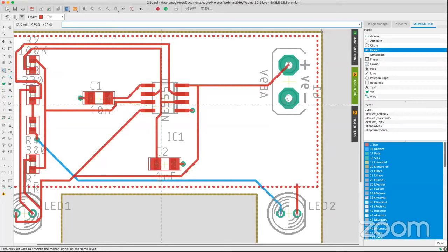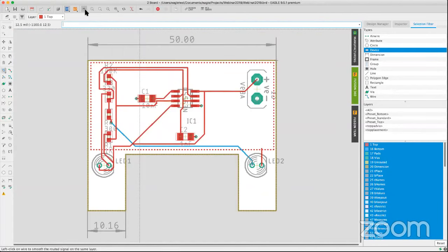So it's okay to go ahead and go crazy and manually route everything on the board as much as possible. And then those that are just really easy routes, like straight lines, some of that, then you may want the auto router to take care of those for you. But we always strongly recommend that you use manual route for as much as you can.